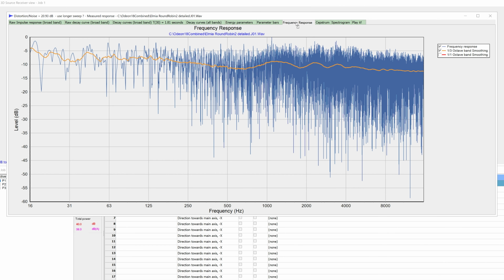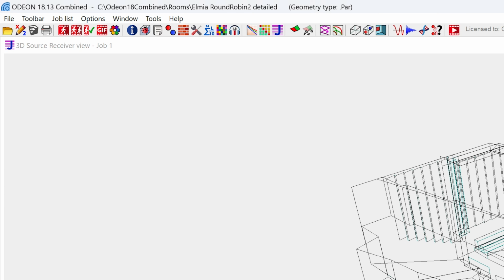Finally, there is a way to obtain the frequency response curve, which requires the room's impulse response. However, the room impulse response is currently being filtered by a head-related transfer function and a headphone filter. This is done by default for the sake of listening to auralizations. But to get a proper frequency response curve, we will need to disable them in the auralization setup.